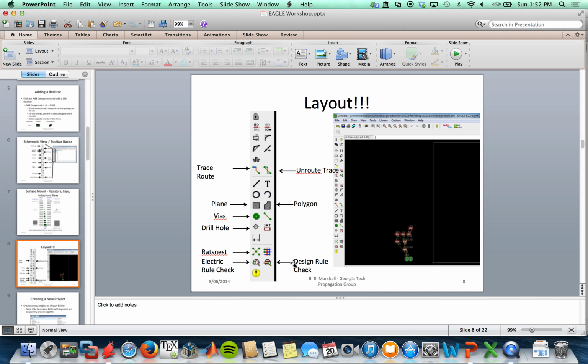It also checks to see if you accidentally overlapped 2 different traces. This is a huge error, so you should be very thankful and make sure you use this DRC check because it will save you revisions and major errors.